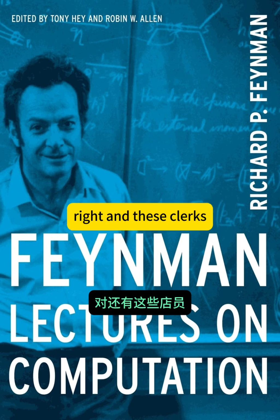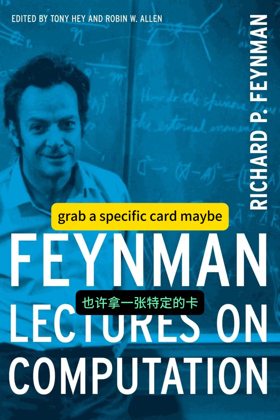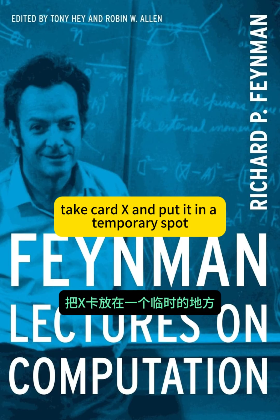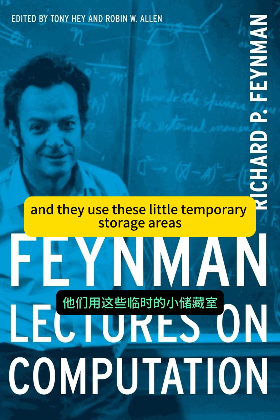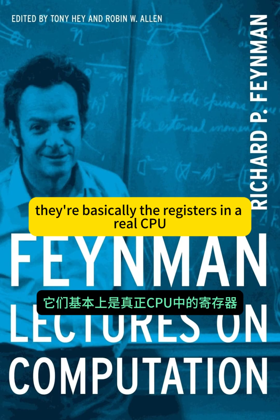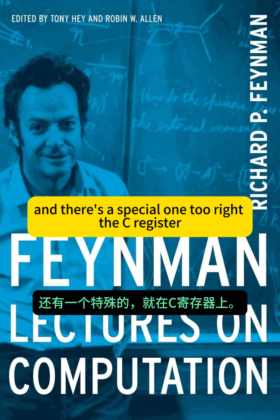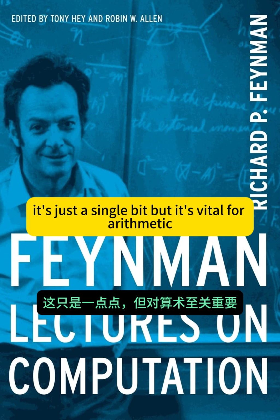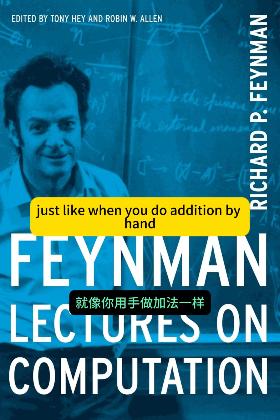Right. And these clerks only do incredibly simple things like grab a specific card, maybe take card X and put it in a temporary spot. Or check what's on a card. Is this card marked California? And they use these little temporary storage areas. Yes, the temporary spots. Those are crucial. They're basically the registers in a real CPU, little holding pens for data, labeled A, B, X. And there's a special one too, right? The C register. Yeah, the C register. It's just a single bit, but it's vital for arithmetic. It holds the carry bit, just like when you do addition by hand and you have to carry the 1.